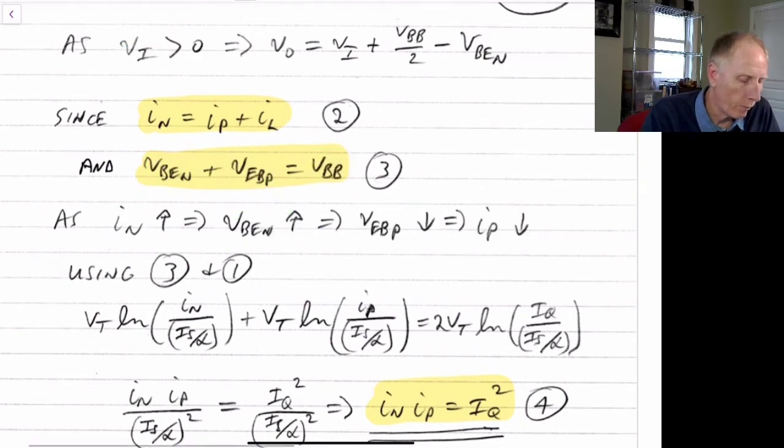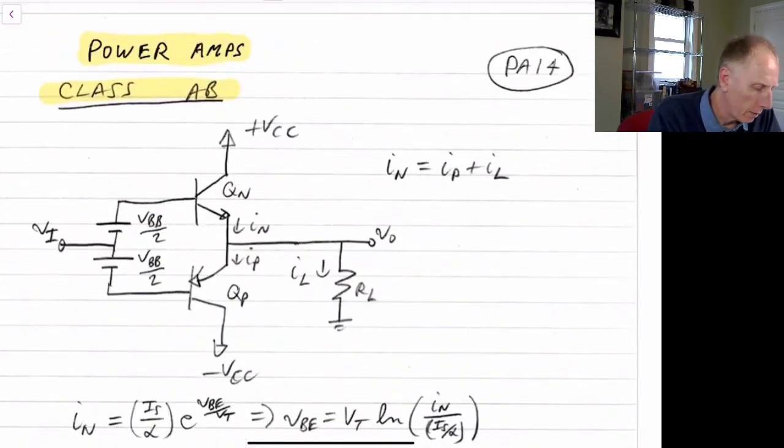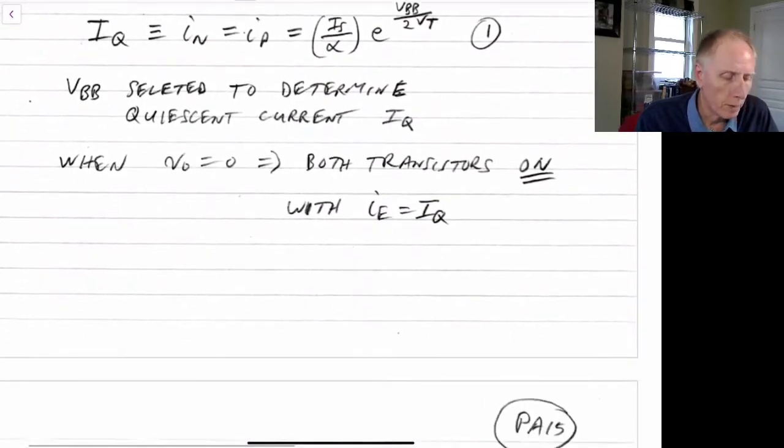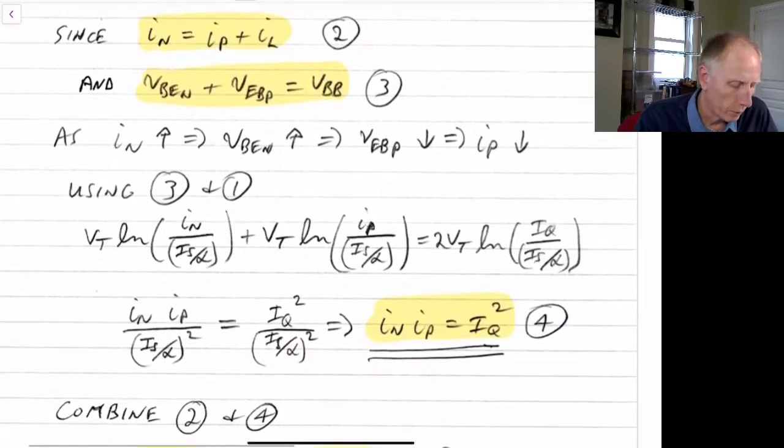So we have what we had hoped for, that as this voltage goes up, this current increases, but this current actually decreases from the quiescent current. So it gets smaller than quiescent current, and we're delivering a lot more current into the load then. And the larger we make this, the smaller this one will become as it goes towards 0. And we've already started off fairly small because our quiescent current, we hopefully pick not too large of a quiescent current. We would pick it usually based upon the largest amount of current that we expect to drive. So some ratio of that.